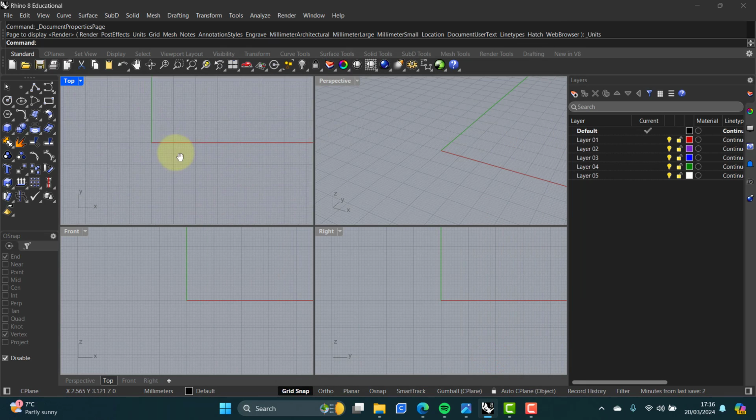the right mouse button, you get pan. Okay, Control on the right mouse button is dynamic zoom, which gives you a smoother zoom in and out instead of the jerky kind of roll of the mouse. Okay, and the left mouse button is generally reserved for selection. So with nothing here, it doesn't do much. Okay, selecting from right to left gives you a crossing window. Selecting from left to right is a gentler window.